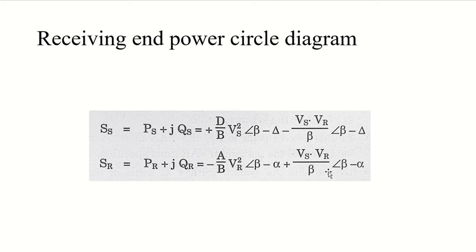we will take the reactive power, right? The transmission lines which we are using are usually operated with constant sending and receiving end voltages. So one component for both the sending end and receiving end power will be a fixed phasor, with a constant magnitude and a particular fixed phase angle.